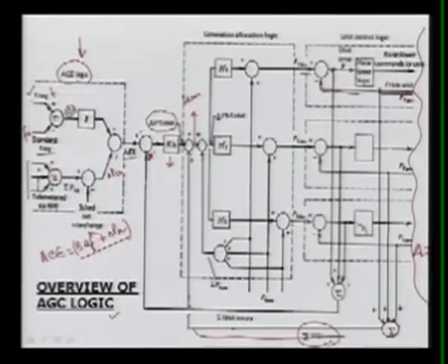As I said, the P base is summed together. Here we take the P base, how much we have to set. Basically this P base comes through economic load dispatch. We know the demand, how much we have to load so that we can achieve the economic loading. So this P base is decided based on these generators, this PGI, and we can get this P base for each individual. So this is now subtracted from here. Now the P total that we require is nothing but P desired minus summation of P base, as we defined in previous equations.